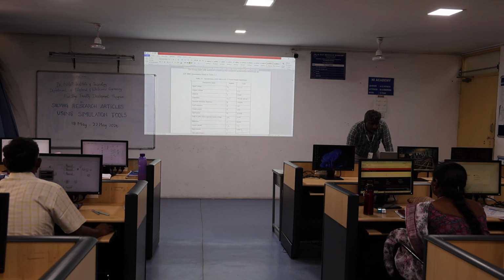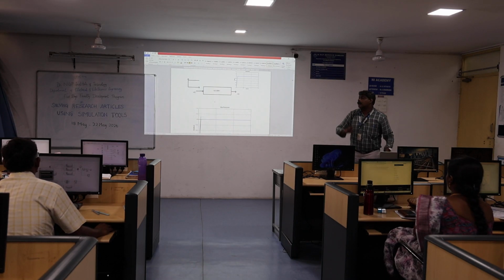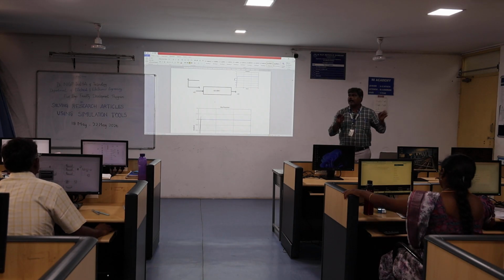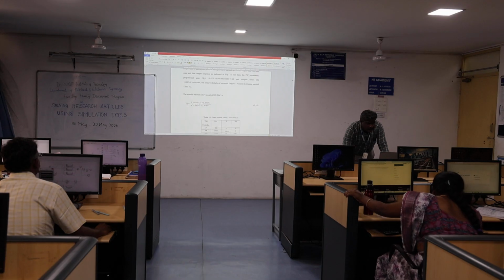So this is the way we are going to form the state space average modeling. Okay, next. So how to do the PI controller design? Okay, so first I know the transfer function. Let us take the transfer function of the system; this is the transfer function.